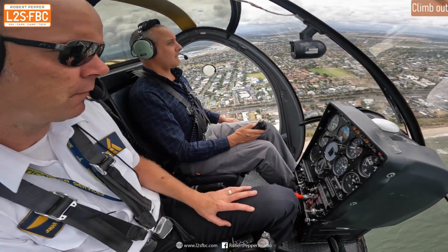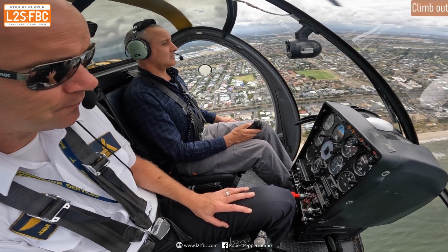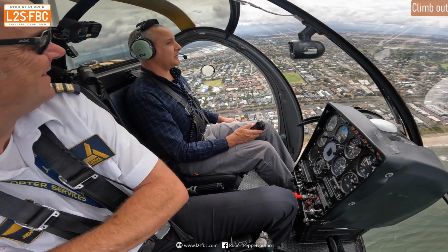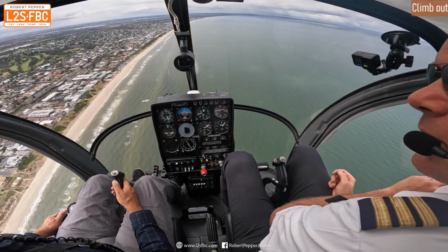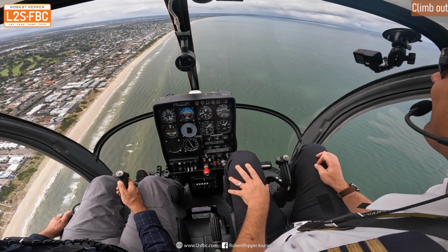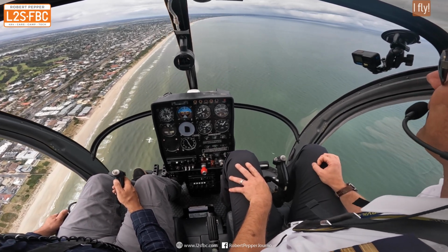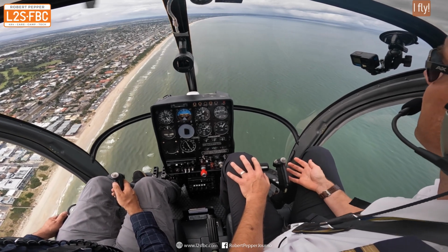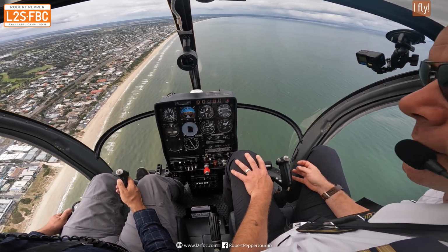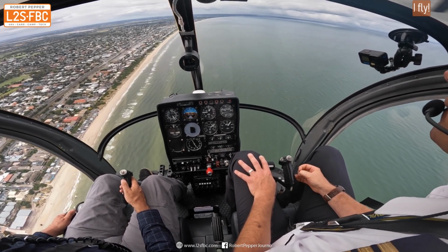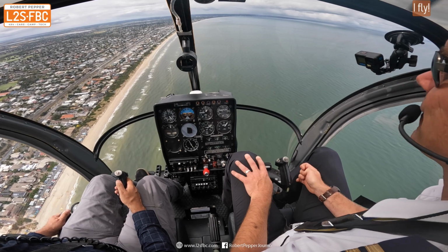Now I'm given complete control of the aircraft, and to do that I'll say I have control, and then the instructor will relax his hands and feet off the controls, or even take them off completely, and I'm flying it. So what I'm doing now is just using my fixed wing experience. So I'm looking well ahead to the horizon, and I've already noted where the nose of the aircraft is in relation to the horizon. I've just got to keep it there with very small control movements.